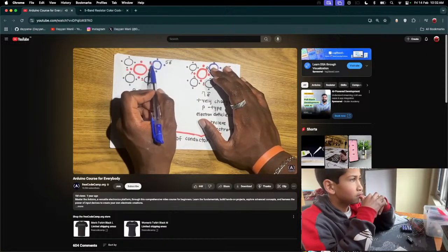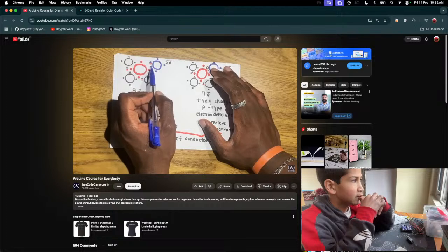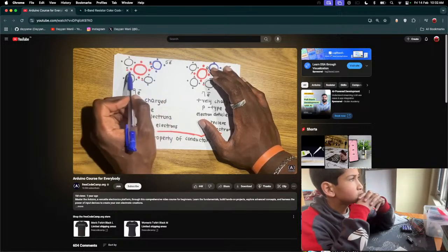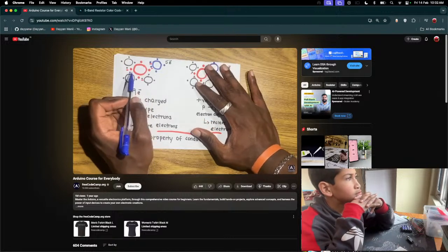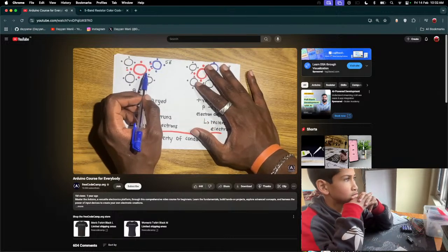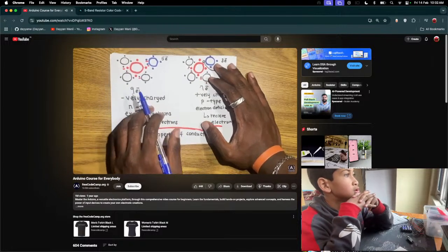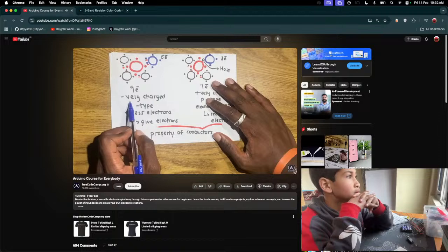So it has 5 dots right here. Instead of giving 1, like every silicon atom, it gives 2. So instead of 8, we're going to have 9 electrons. We could even count it: 1, 2, 3, 4, 5. We have 5 shared electrons, and we have 4 valence electrons that we already have on the silicon atoms. When we add that up, it becomes 9 electrons.